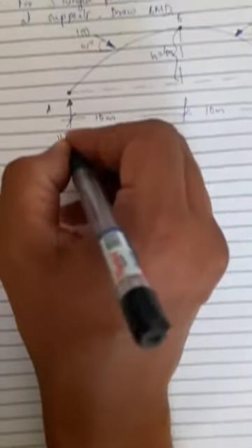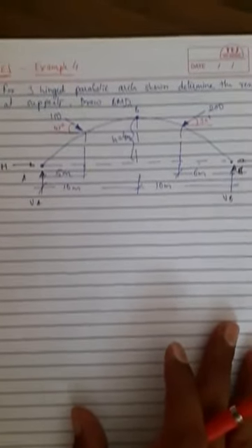Let VA be the vertical reaction at A, H, VB, again H. Let these distances be given as 6 meters, 5 meters. Now since the loads are inclined, we need to find the resolution of forces in horizontal and vertical directions.